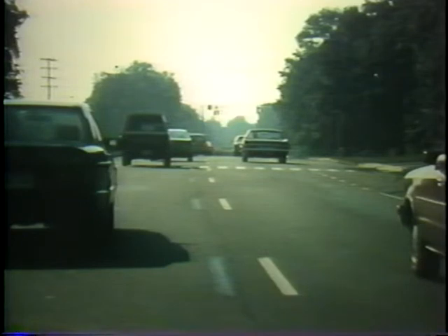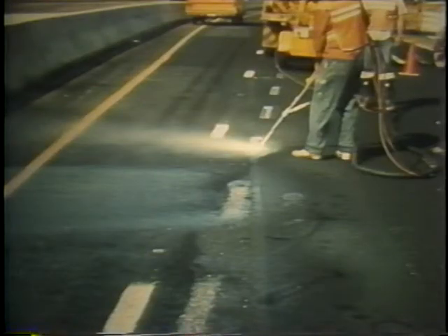Removal of old pavement markings frequently creates delineation problems because glass beads in the paint still provide retroreflectivity at night. Painting over old markings is not acceptable. Drivers would be confused if this were done, but removal of paint lines costs more than $1 a foot for a 4-inch line. Burning, grinding, or sandblasting all have one common problem.